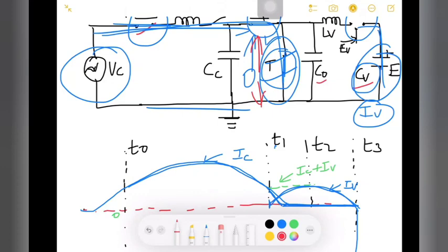So it is important to see that the high current source is disconnected when you are applying a high voltage, and the high voltage source should be applied at precisely that time. That is an additional arrangement we need within the circuit. When the current becomes 0, we remove the current source generator and apply a high voltage source to the circuit breaker by means of the auxiliary circuit breaker.